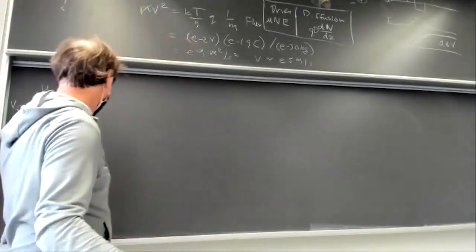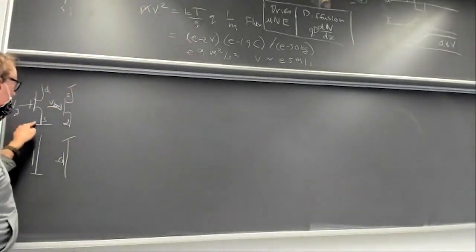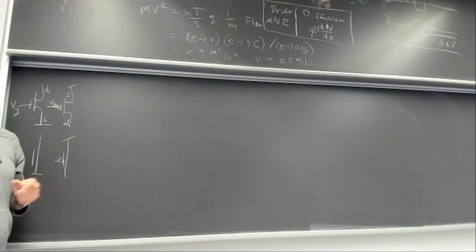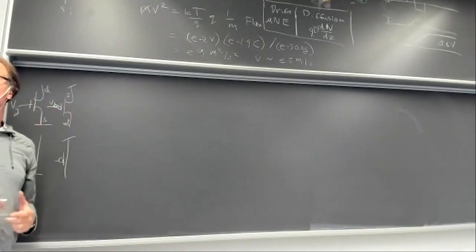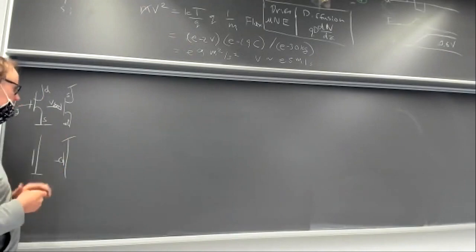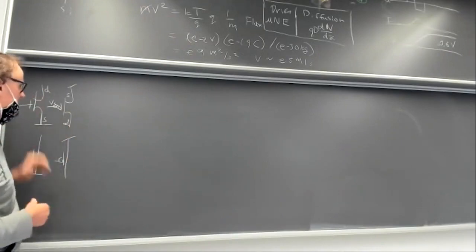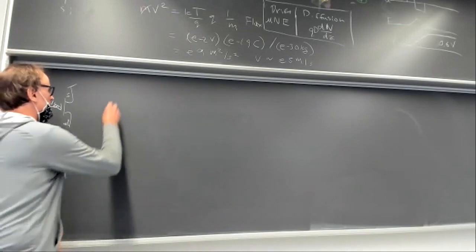Just like that. As long as the drain to source voltage is big enough, the current's not affected by the drain voltage because the electrons just fall out. Okay? It's only when the voltage difference is small that this voltage matters.